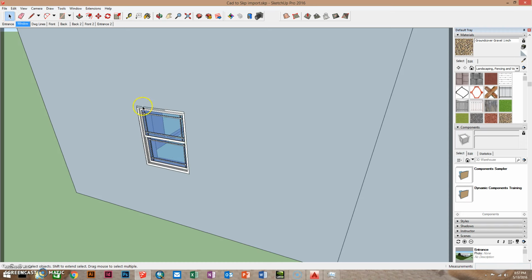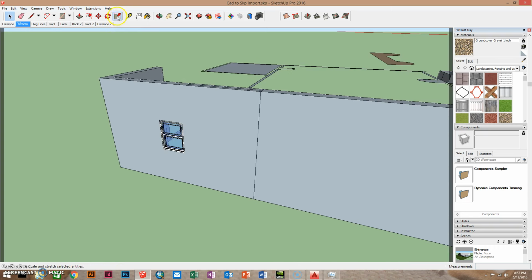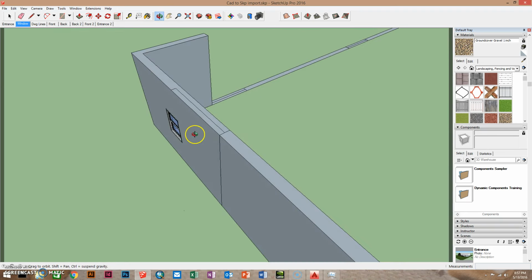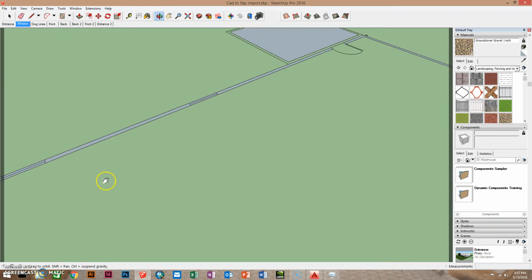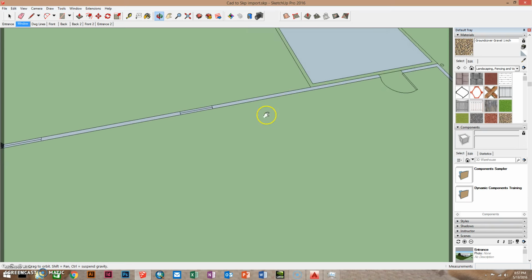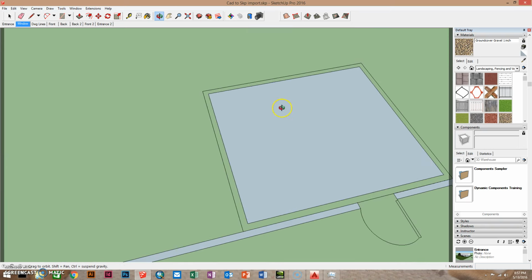So then you're going to want to just go into the 3D Warehouse, which I'll go into in a second. That'll be step 4, which will be step surfaces and components. Step 3, this is the 3D phase, blowing it up into 3D. And I'll just show you over here. If you hold down shift while you're in orbit, it'll actually let you pan.